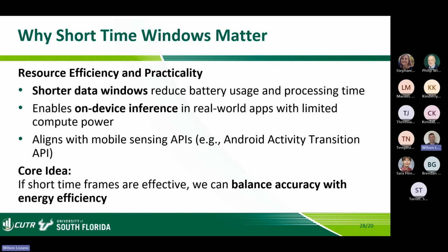Why short time windows matter? This is related to resource efficiency and practicality. Shorter data windows, if we are collecting data, mean we are using the sensors only during that time frame. A shorter window is going to reduce battery usage and processing time, and can also enable on-device inference in real-world apps with limited computing power.